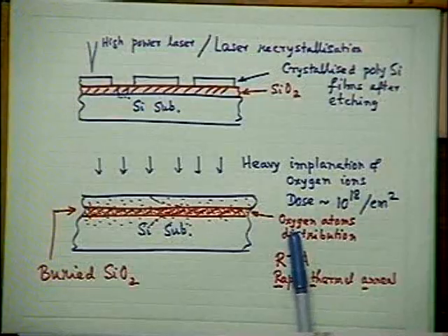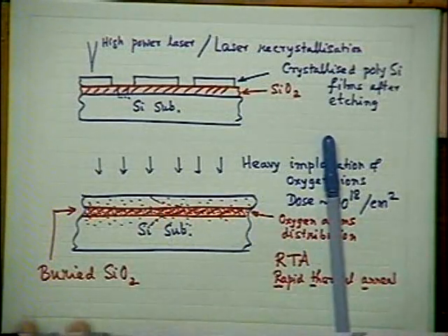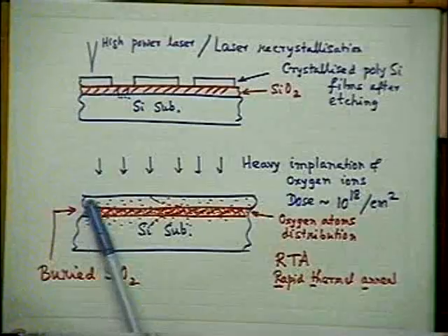What I say is that as you anneal, two things happen. Firstly, the oxygen distribution, though it will have a tendency to disperse because of redistribution and thermal diffusion, but because of the bond formation, there is a reverse process by which there is a conglomeration of the oxygen atoms, and they try to form the silicon bonds, Si and OO form SiO2. Double bonds, Si with two double bonds to O, form SiO2. It will try to form that.